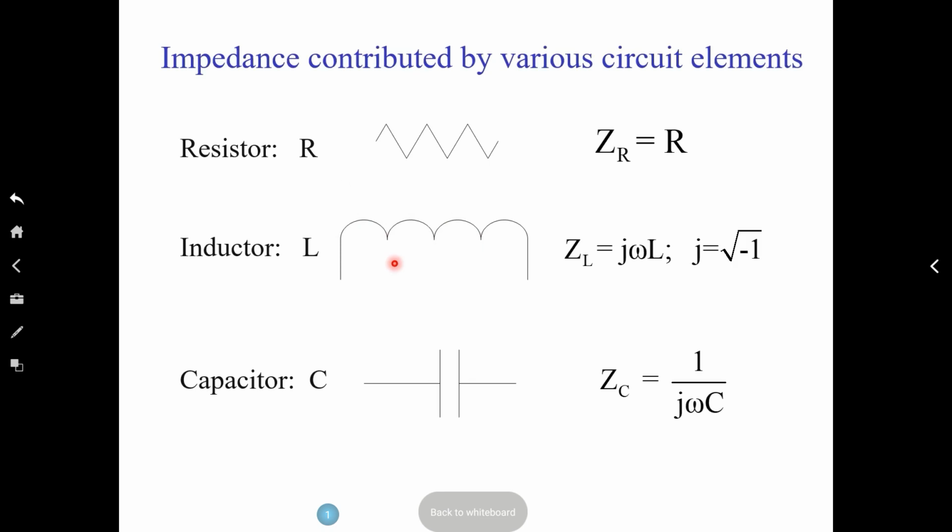For example, if you have a sample inside a furnace and you're doing high temperature measurement, or most ceramics, high temperature that you have to measure, and the lead wires are coming out of the furnace. And if these lead wires are not bent, and if they're sagging, then you will get this electromagnetic induction that will show up in your impedance value that you measure as a component L. So you will need to use L as a subtraction. That's not really a sample behavior. You don't really want the L, yeah?